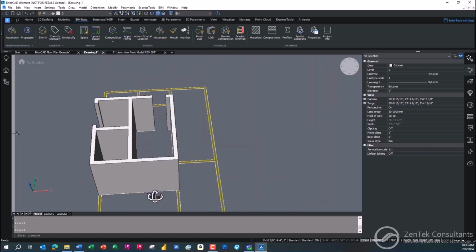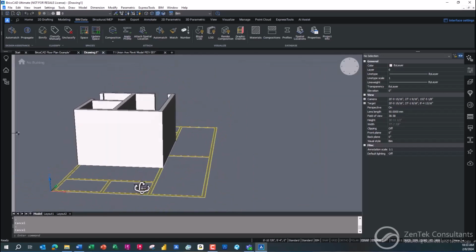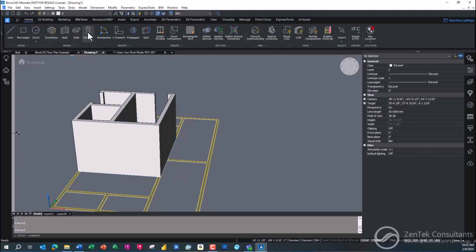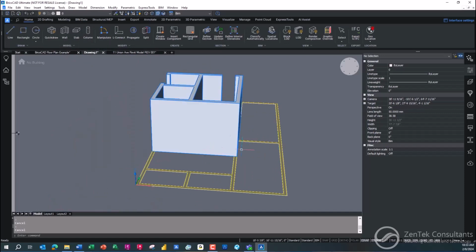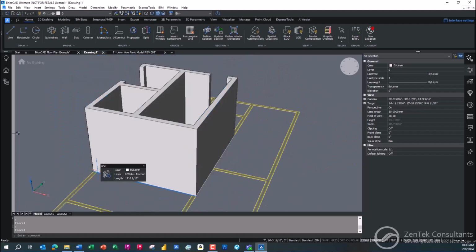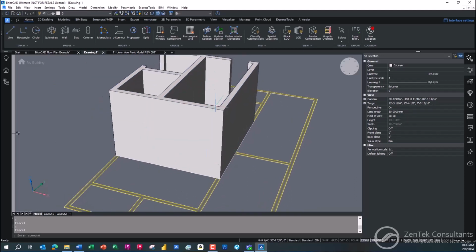Right? And using these walls, I can easily go in and measure and check heights and clearances and conflict potentials as I'm moving equipment in or out. And it's very, very easy in here to do things like draw columns and boxes and slabs for pieces of equipment and see if they'll fit through doorways. Using this kind of localized BIM structure, you don't necessarily have to have the whole building defined in 3D. You can just go in and do individual rooms or individual areas that you just want to verify.